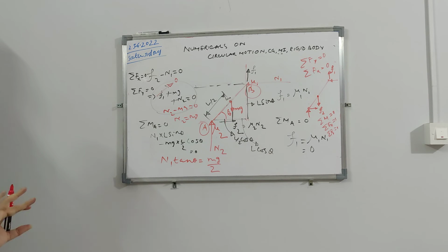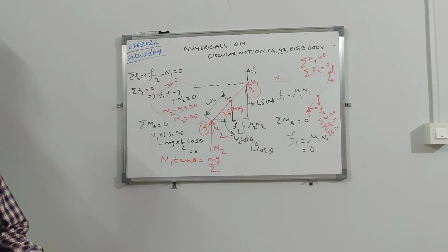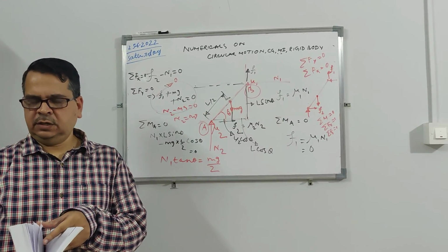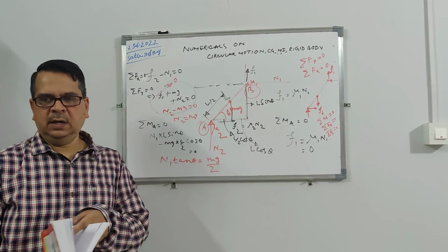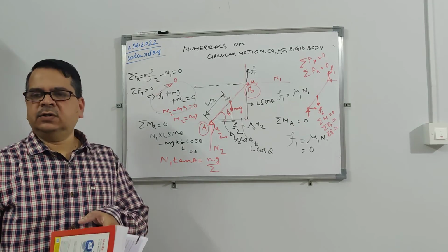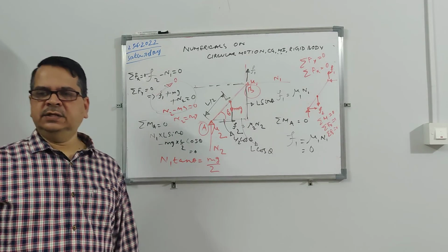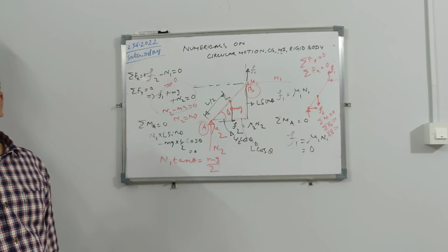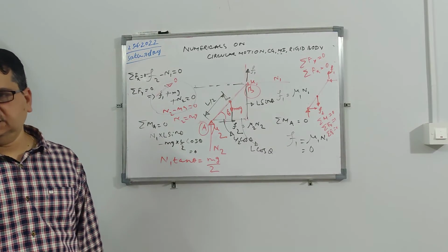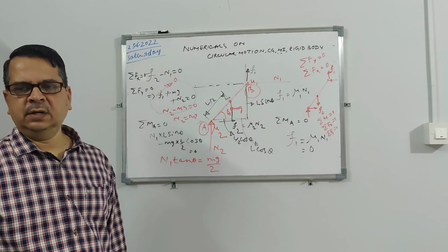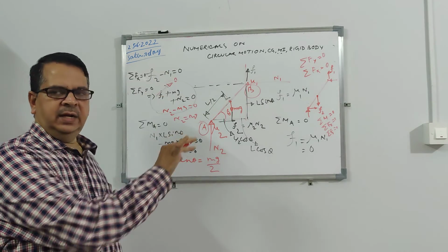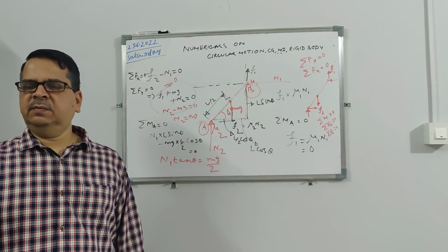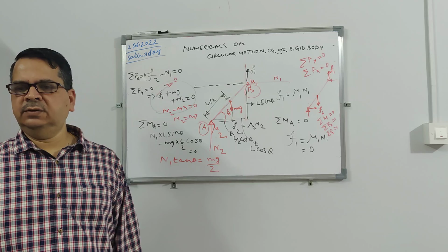So with this concept you can solve any problem in statics. Now we have done problems on moment of inertia, center of gravity, and rigid body equilibrium. These are otherwise called problems in statics, and this is only rigid body, so there can be a lot of numericals. Just remember moment of inertia, the parallel axis and perpendicular axis theorems, and practice. The main thing is understanding the concept. Statics is all about sigma Fx equal to 0, sigma Fy equal to 0, sigma M equal to 0, and drawing your free body. That's all.